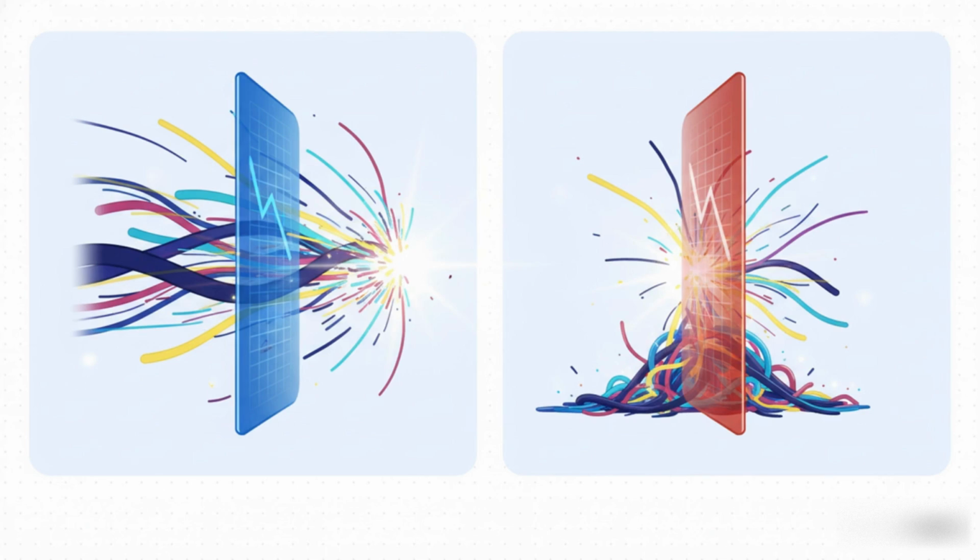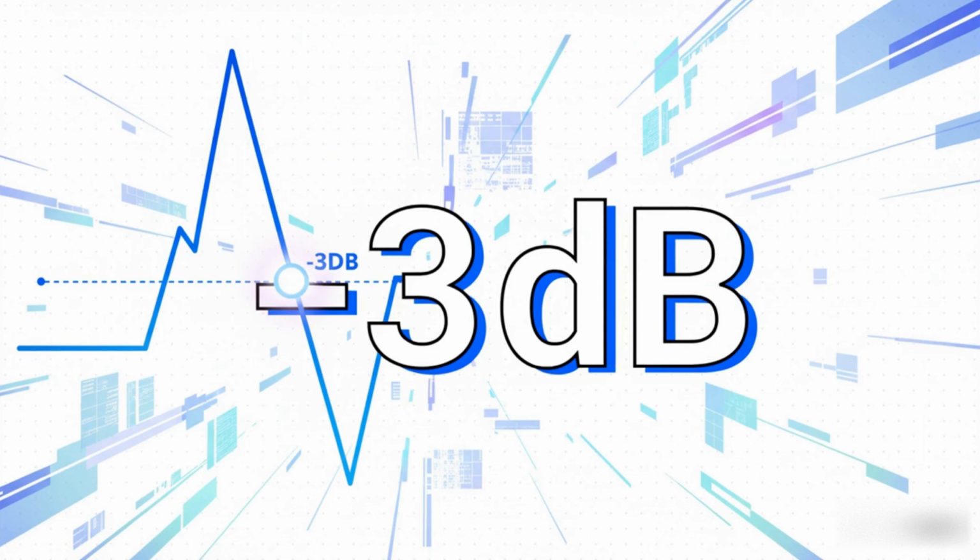So, how do you know where the bandwidth begins and ends? How do engineers define that edge? They look for something called the half-power point. It's the exact frequency where the signal's power has dropped by half of its peak. That's the cutoff. And in engineer speak, that half-power point has a special name, the 3 decibel point, or the 3 dB point. That's the magic number that marks the edge of the bandwidth.